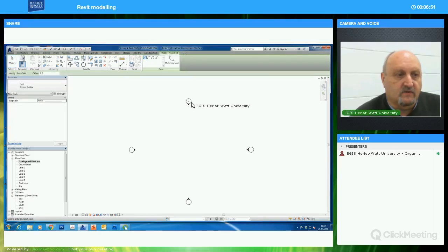I'm just going to randomly start up here. These are the elevation markers, north, south. This one's west, this one's east. I'm going to ignore those for the moment. I'm going to randomly start at some area up here. And if I hold the shift key down, I can force that to be straight vertically. And I'm going to do that.